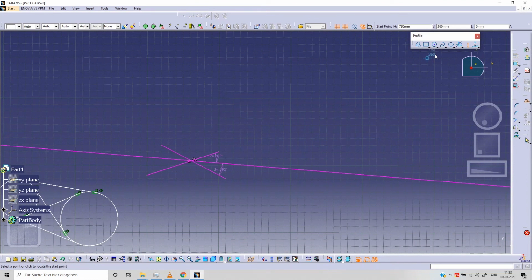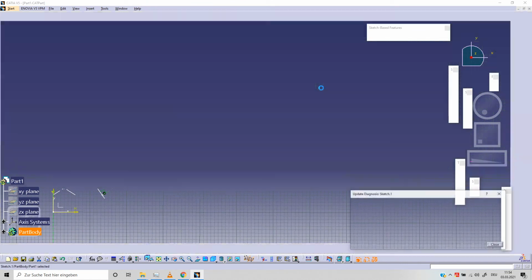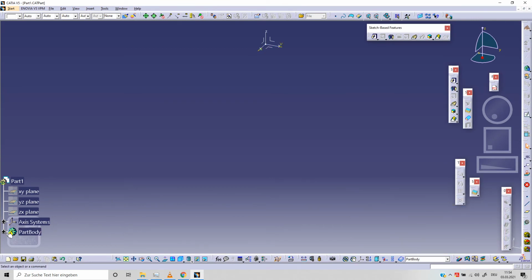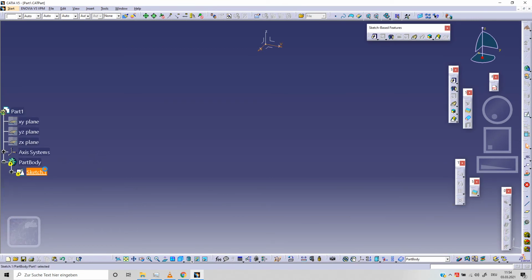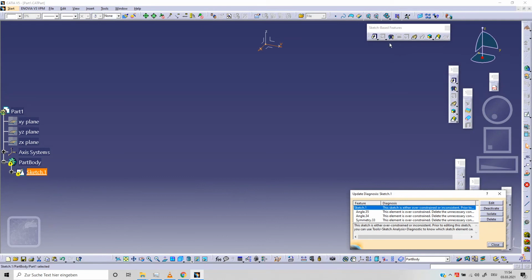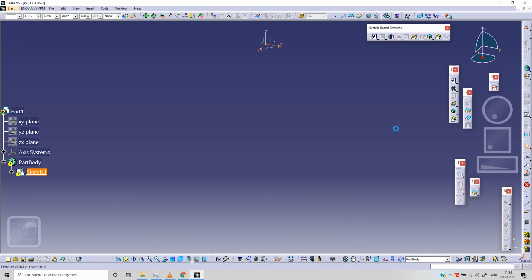And lastly we can use this axis. This is a line. This is a construction line. If I flip in our 3D space, we cannot see this line. Okay, we've got a problem with our sketch, but this line still exists, and we can use this line to create something like a shaft, or what else? We can use this normally for shaft, yes, and even for other commands like this groove, yeah, close.